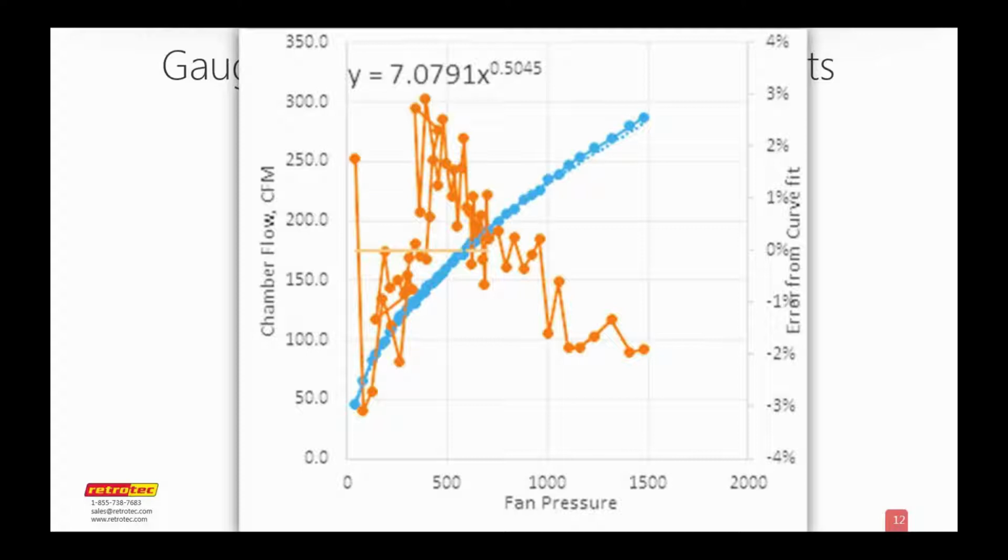When we're comparing a window to a hole in a flat plate, a window won't come out to read exactly its hole size because of the detail of the edges and how it allows the air to flow into that hole. So it will measure as being a smaller hole than it actually is.